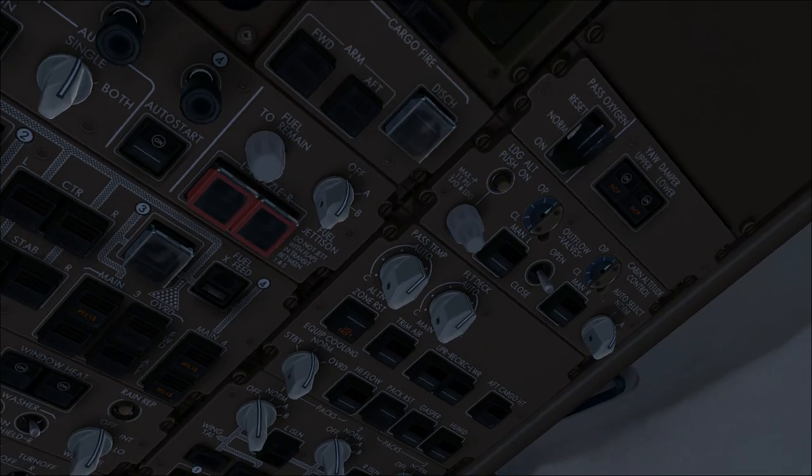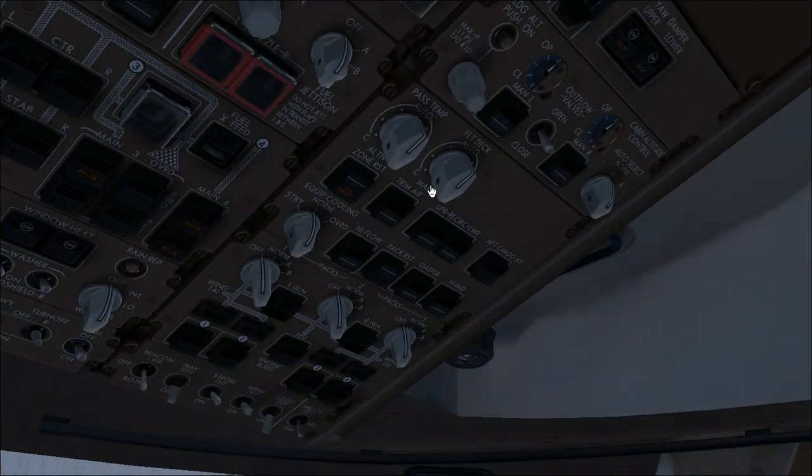Coming back to the cabin altitude panel, you have to check hold flow valve manual switches in off, these two are in off, and cabin altitude auto selector in normal, and this is checked. Hold flow valves are open, and this is fine, and we can move to the ACS panel or environmental control system panel here. Passenger temperature selector and flight deck temperature selector in auto, they are vertical switches in auto. We have to select trim air switch on, and at this point we have the zone system fault light extinguished because we have turned on trim air. This is actually normal. We select upper recirculation and lower recirculation fans to on.